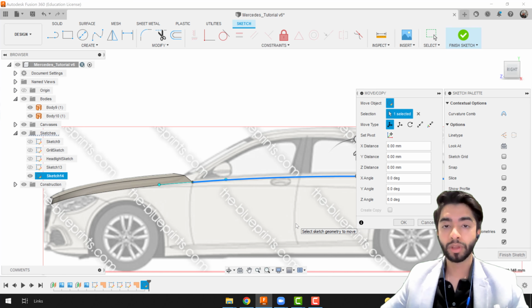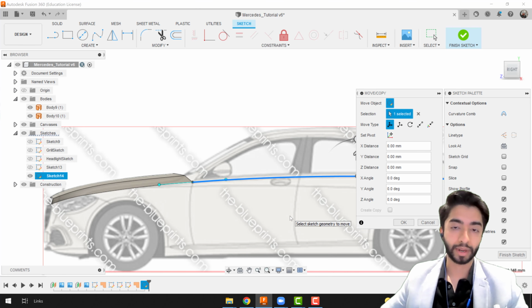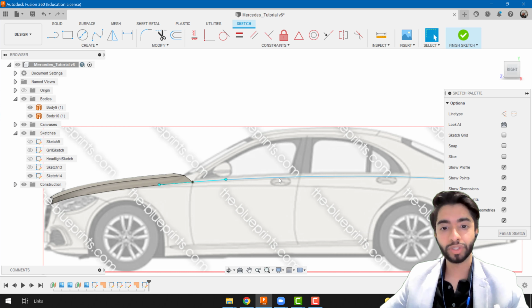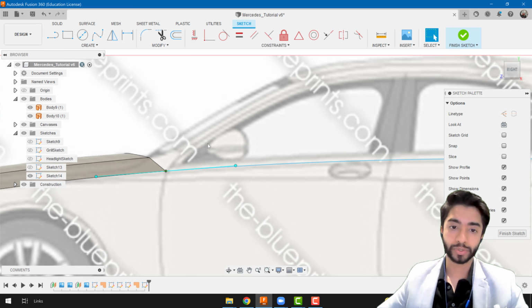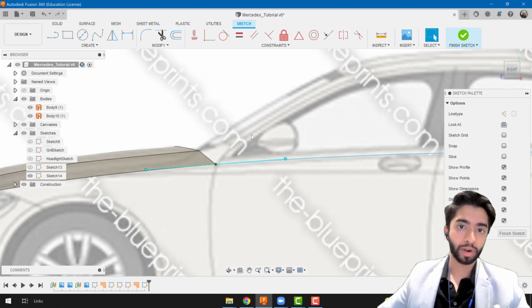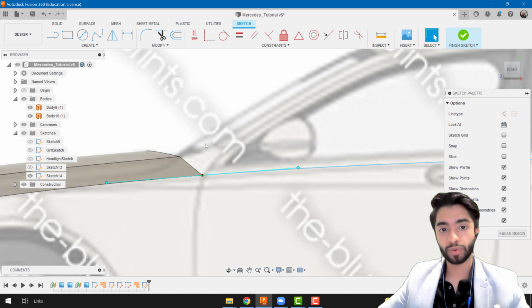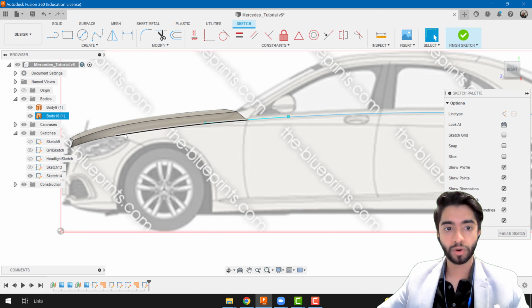See what just happened? We took an edge that we made in the previous sketch, we broke that sketch, copied that new edge that we created, and pasted a brand new one into our current sketch. Now we can actually use this, add some more details around it, and then start using the break feature again to create our individual surfaces. So I've given you a good starting point. Try this out yourself. And in the next video, we'll create that surface over there, as well as this surface over here.